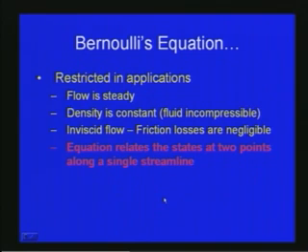As far as Bernoulli's equation is concerned, it has some restrictions. This Bernoulli's equation is derived based upon the assumption that flow is in steady state, so the time component is not there. Flow is steady and density is constant, so that the fluid can be considered incompressible. And then of course we also assume that the fluid is inviscid, so that the friction losses are negligible.